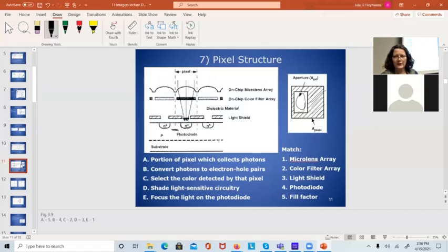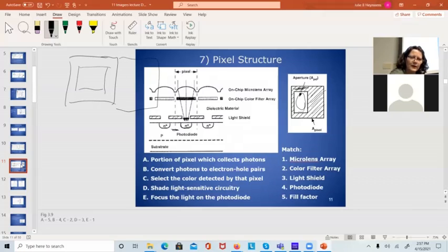Now, astronomers got highly upset if they didn't have 100% effective fill factor, even though we have to put transistors in there. So we would squeeze our transistors in up here, and we would do this symmetrically. We would do this more symmetrically for a science grade device, and then have the next adjacent pixel right here, with no filters on top of it. So light that hit right here would actually end up being equally divided between the two pixels. That was one of the tests I had to run.